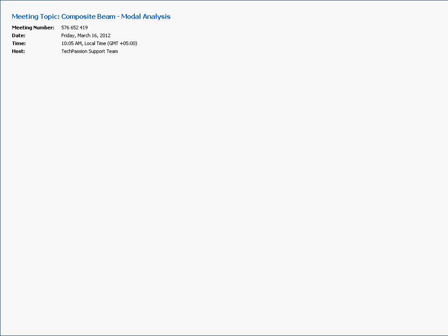In the examples that I showed you, I either showed the simulation or the testing. But there are case studies where we have been able to take the test data and look at the simulation data as well and calculate the MAC. The MAC is plotted on a scale of 0 to 100. So if you have 100, that is good, a perfect correlation. If it is 0, there is perfect lack of correlation.